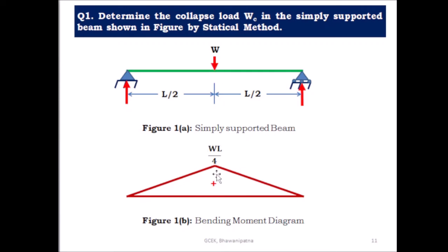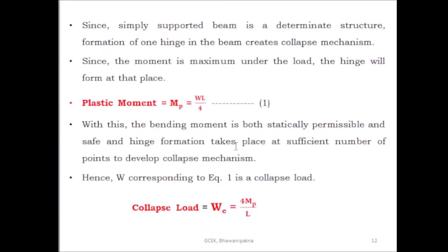So we know at the loading, what is the bending moment here? The bending moment here is equal to WL by 4. So WL by 4 is equal to the MP. The plastic moment MP is equal to WL by 4.